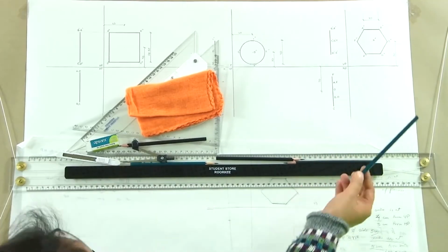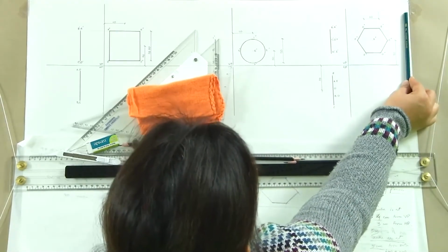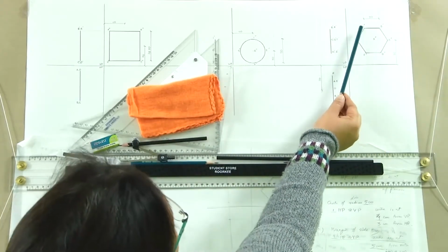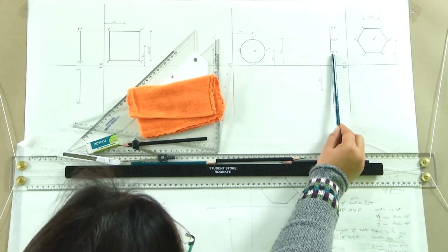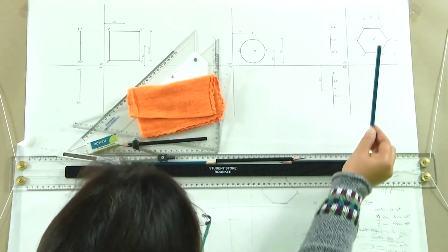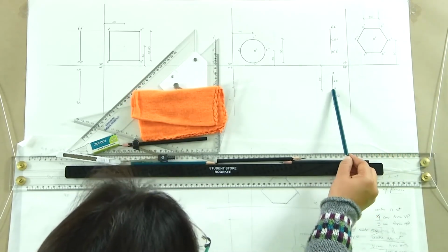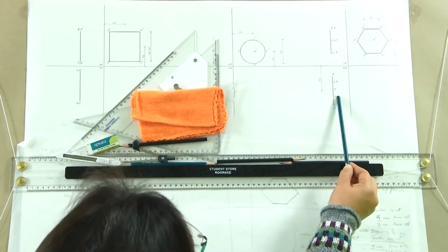Now, we will do the labeling to mark what is seen. So, the center was marked as O and the hexagon A, B, C, D, E, F, and if you look at it now, what is this point? This is point B seen first, because we are seeing from this side. This is the front, because this is VP, so we are seeing it from this side. So, B dash, A dash, C dash, O dash, F dash, D dash, E dash, which is here, and when we see it from the top, what do we see first? We see A, B, we see F, C here, O in the center, and E and D beneath A and B. So, A comma E and B comma D in the same position.